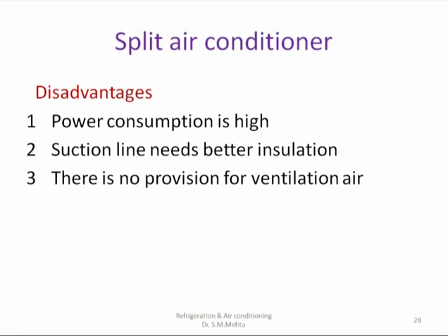But there are disadvantages also. Power consumption is high, the suction line needs better insulation, and there is no provision for ventilation air. These are the various disadvantages of the split air conditioner.